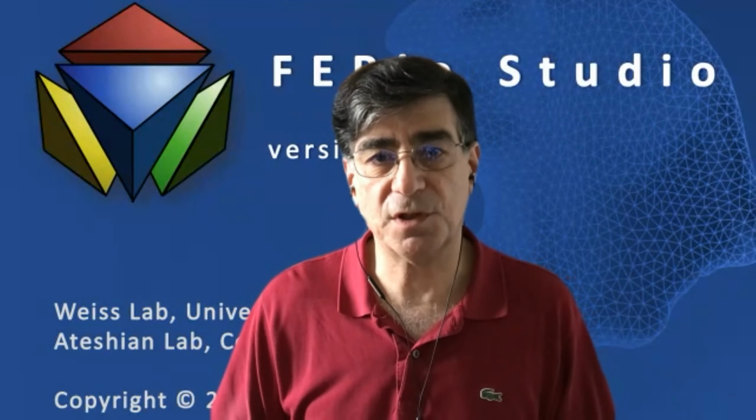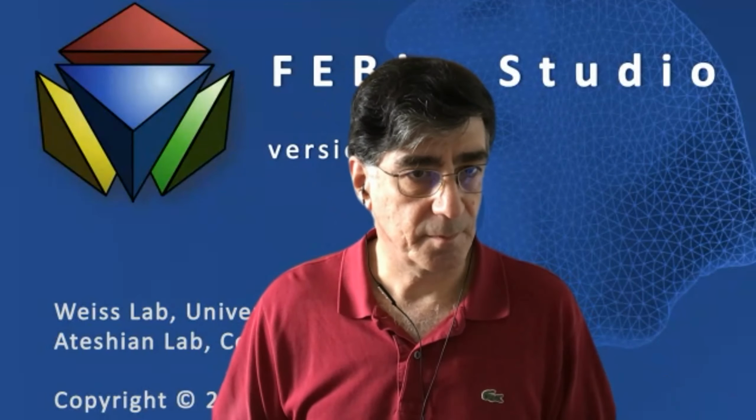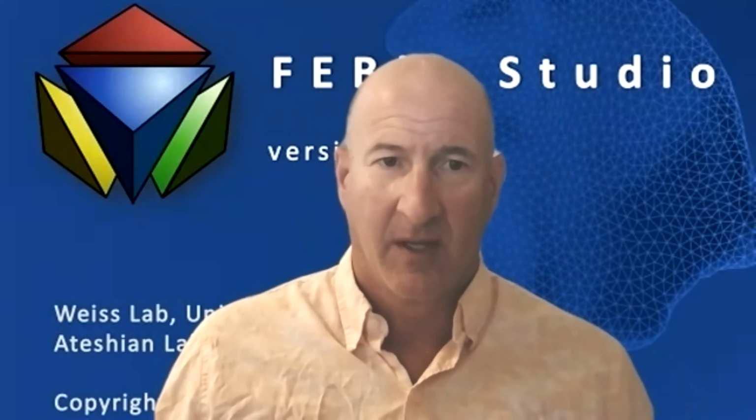Now, if Jeff or Steve have something to add to this, please do so. I've never tried the 3-field elements with higher order elements. The main element that we implemented it for initially is the 8-node hex. So for that element, you have a trilinear interpolation of the displacement and a piecewise constant interpolation of the pressure and the Jacobian of the element.